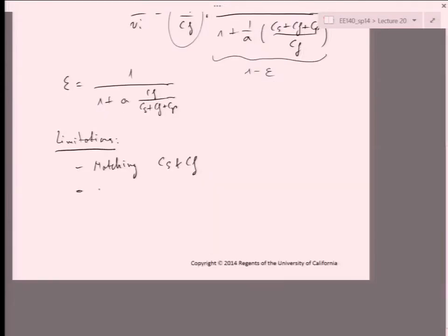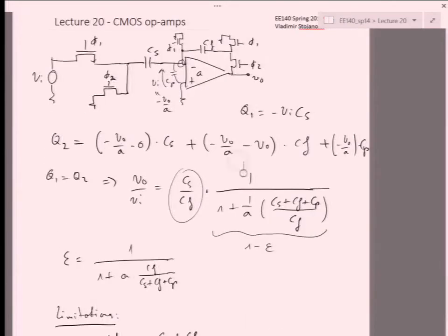Then large open loop gain. We'll see. So offset is non-zero. So offset will sort of play a role here because it will be the voltage that will prevent things from getting completely to virtual ground. So your parasitic capacitor will be charged with that as well.